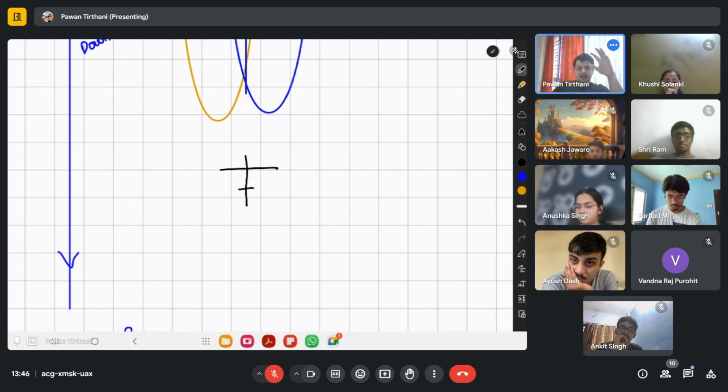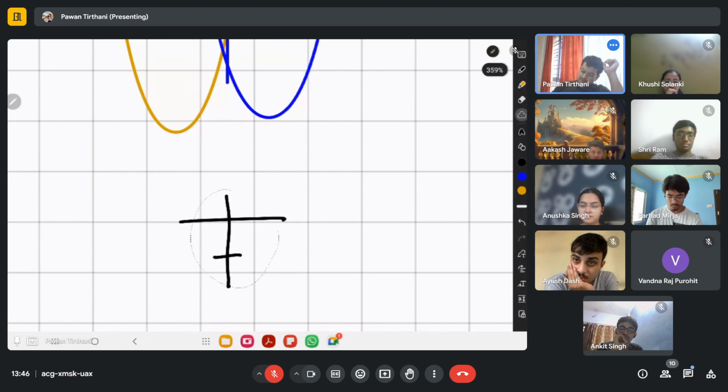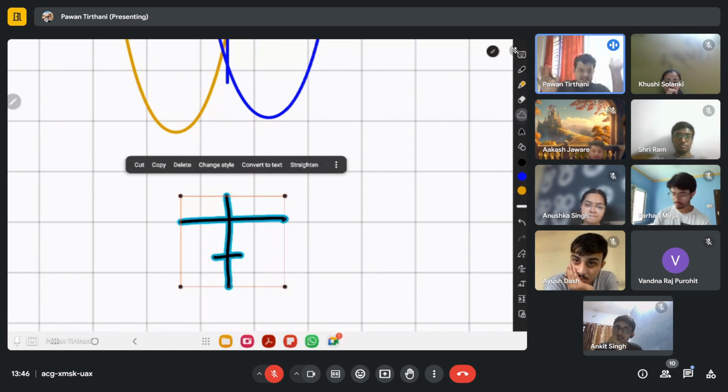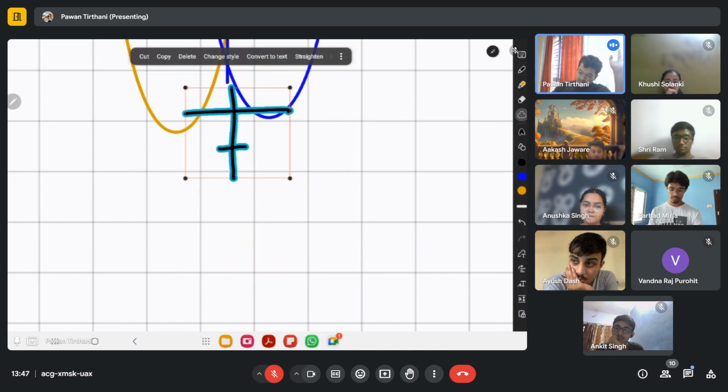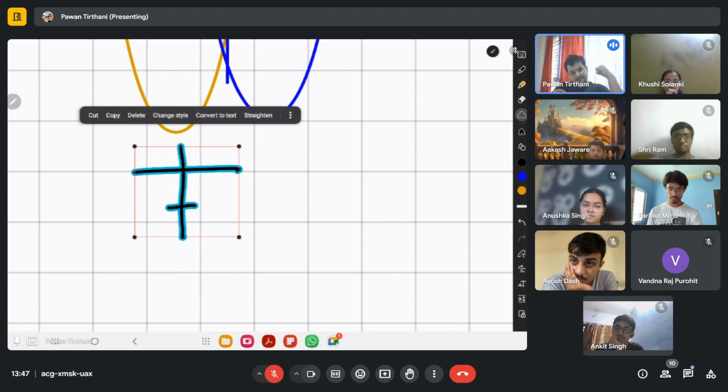Okay, now let's say I have this aircraft. I'm in clouds, I can't see anything. My aircraft cannot see anything. Now, if my aircraft is on the left hand side, am I receiving more of the 90 hertz modulated signal? Is the 90 hertz modulated signal more deep?